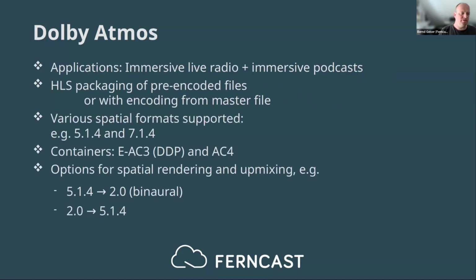Okay, I'll switch over to Dolby Atmos. The applications here are immersive live radio and immersive podcasting. The use cases we support here are packaging of pre-encoded files, which come from a Dolby Atmos production studio, or we can provide encoding from a master file that comes out of that ourselves. We have various spatial formats that can be supported, 5.1.4, 7.1.4, or others. Dolby Atmos is packaged in containers, the Dolby Digital Plus, the enhanced AC3, or AC4 usually.